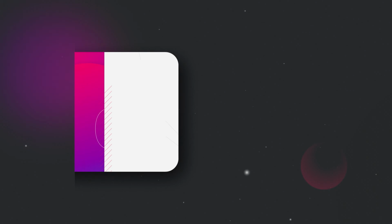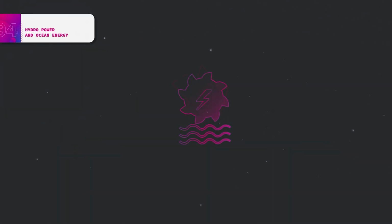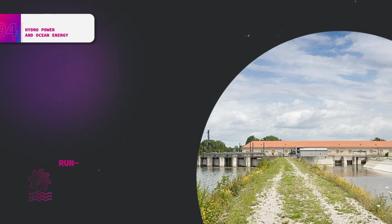Hydroelectric power plants use potential energy and natural elevation differences to generate electricity. Run-of-river power plants use the natural elevation differences of a flowing river. Using a weir, water is backed up and powers a turbine when released to the lower water level. This turbine is connected to a generator that converts kinetic energy into electrical energy.